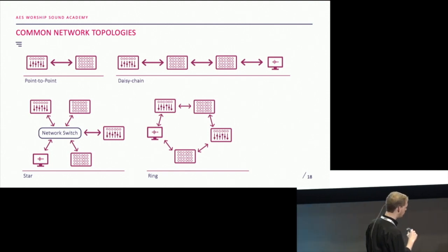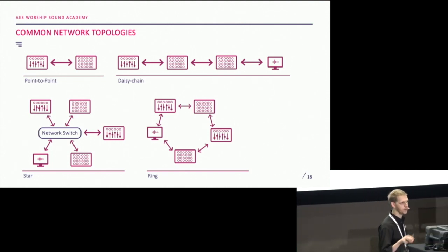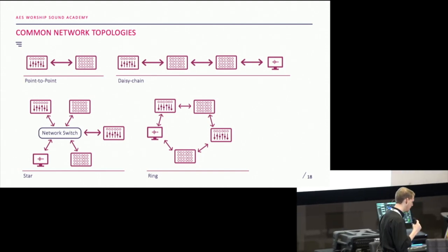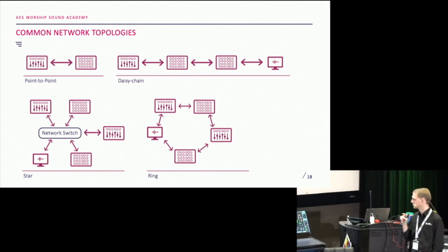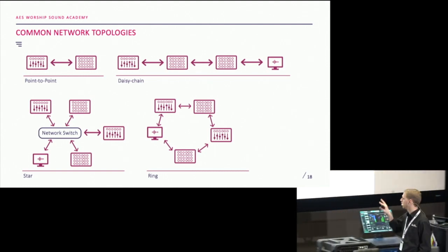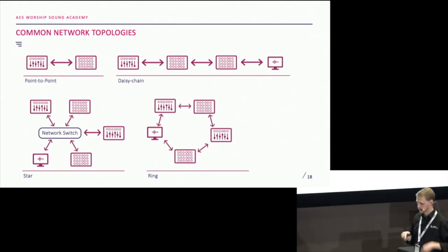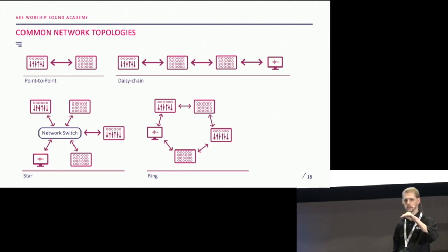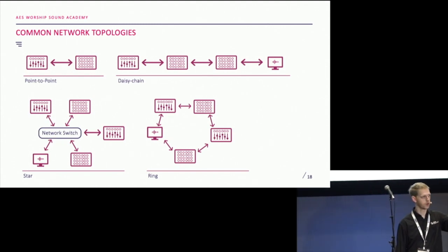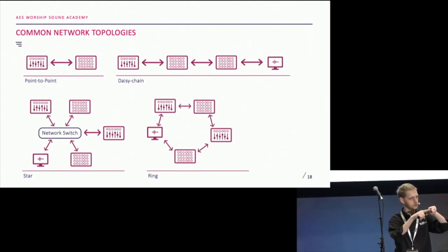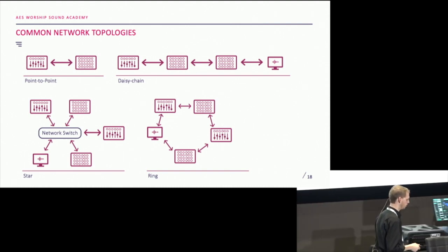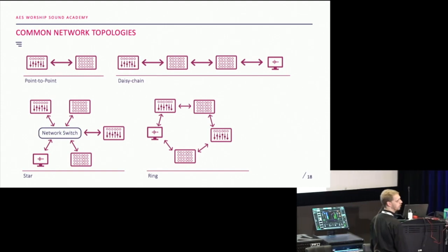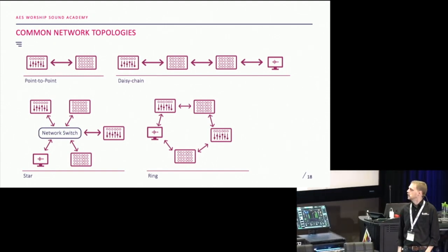So, hey, is there some way that we could build in some redundancy outside of what our manufacturers may offer us? And that's when we can get into a ring configuration. The ring configuration allows us to connect multiple switches. I've drawn them as devices, but we should really think about them as switches. We can connect these switches into a ring so that if one link goes down, the data is traveling this way, this link dies, it stops, it says, oh, this one's dead, I'm going to start going back the other way. So now we've got a continuous flow, and really you're looking at only a second or 2 of loss of audio as opposed to complete, total catastrophic failure.